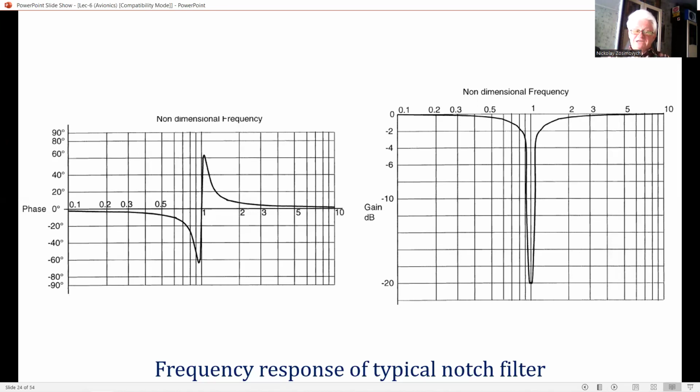For example, a time delay of 10 milliseconds produces a phase lag of 7.2 degrees at an input frequency of 2 Hz. At 10 Hz, the lag is 36 degrees. The amplitude, however, is not attenuated as the frequency increases, as is the case with a simple lag filter, and so the destabilizing effect is worse.